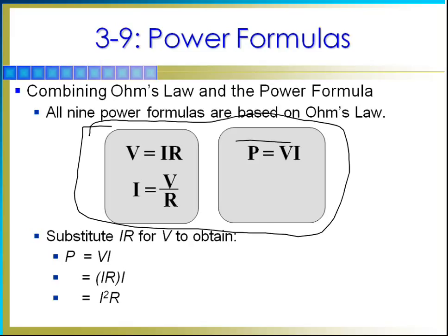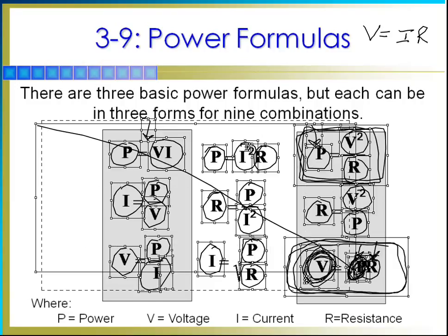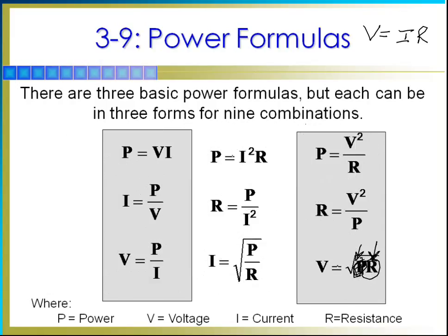You want to remember your power formula and how to substitute Ohm's law into the power formula to create your 9 different forms of power.